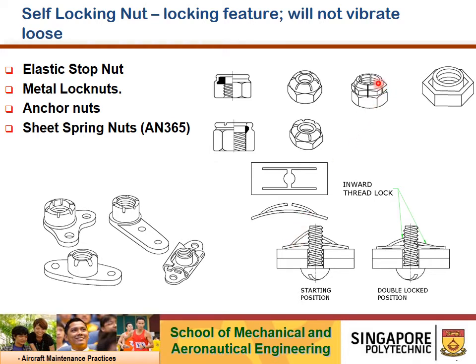Alright, so metal locking nuts are primarily used in a high temperature area, which I mentioned earlier. The locking action depends upon the resiliency of the metal when the locking section and load carrying sections are forced into alignment when we engage the bolt.